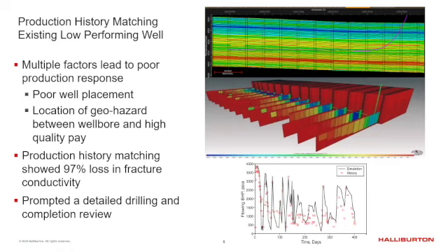And so we fracked these wells and we pumped millions of pounds of sand and millions of gallons of water. And we got almost nothing out of this well. We got a tiny bit of gas, but almost nothing. So to model this from a production perspective, doing production history matching, we had to damage our fracture conductivity by 97%. So that's telling us there's no fractures down there. But I know I placed the sand. I know I pumped the water, but I'm not seeing any fractures. That's what it's telling me. So this was a bizarre finding for us.